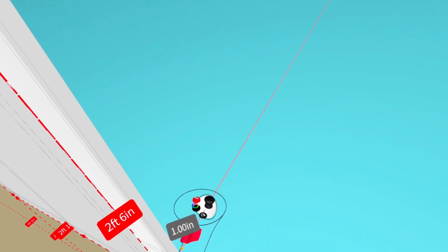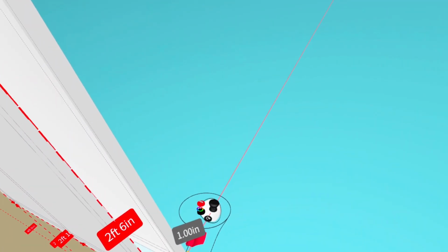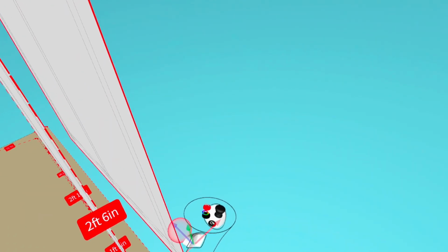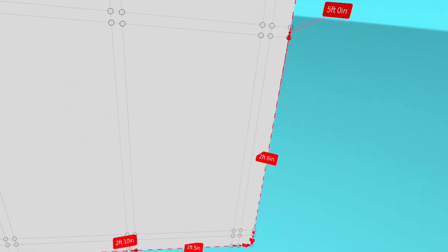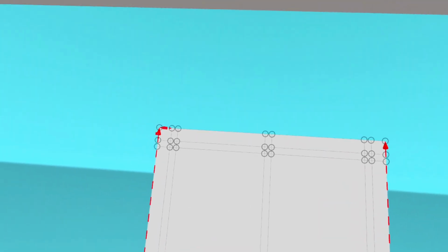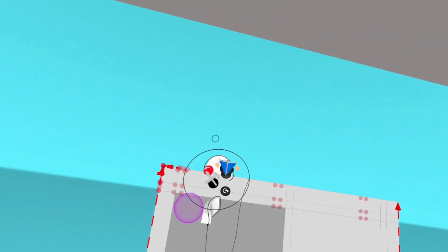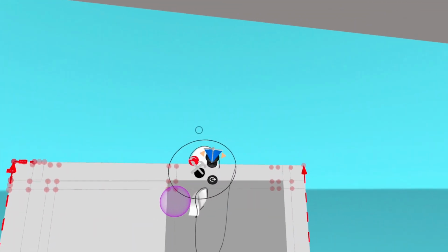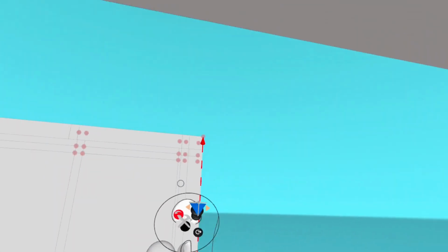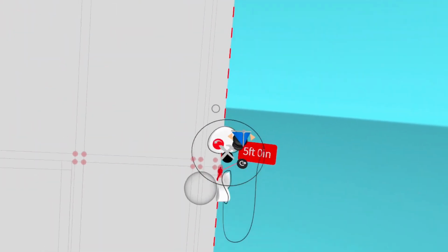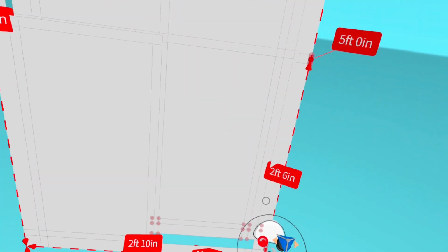I'm going to make a copy, and I'm going to move it back about 4 inches, just 1 inch at a time while using the smart move by aligning my controllers. And now I've put the first sub D objects into edit mode, and I'm going to start deleting some of these faces, basically everything but the very outside faces, because this is going to be the casing.